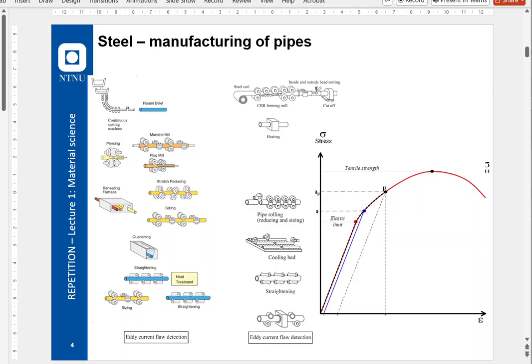We also remember that what is in the colored part to the left is seamless pipe, meaning that there's a physical rod coming out of the steel melt, and that it is pierced. You can see it's kind of small here, but it's pierced with a spear, and then it becomes hollow, and then it is worked over and over again until it has the right properties. Through this process, it is reheated and cooled off in order to keep the right properties of the pipe.